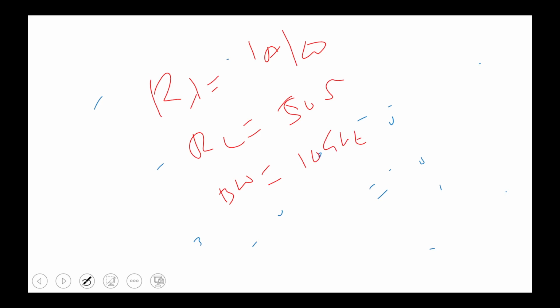We have no distortion in the waveform, and considering only thermal noise and signal ASE beat noise. So there is no shot noise in the signal, no power noise or any other noise, Gaussian noise, Schottky noise, filter noise. There is no noise of that. Only you have to consider thermal noise, sigma T. Okay, find the receiver sensitivity for Q equal to 7 with the OSNR. So from that, for Q equal to 7, how much is the bit error rate? I think that is 10 to the power minus 12 bit error rate.